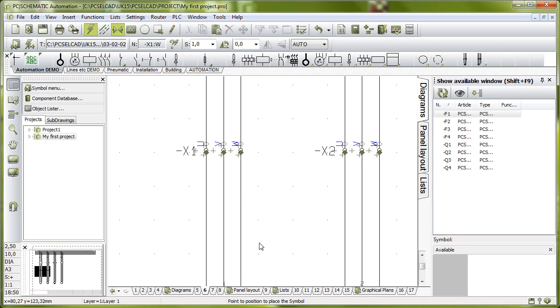Terminals, this part is not very difficult, but when you look at terminals, beware that you have connection points here, and one is white and one is green. And if you look at the white one, you can see in the lower line that it's got input status. That means that this is the internal side of the terminal row. Normally that would be the outward side of the terminal row if you look into the panel.